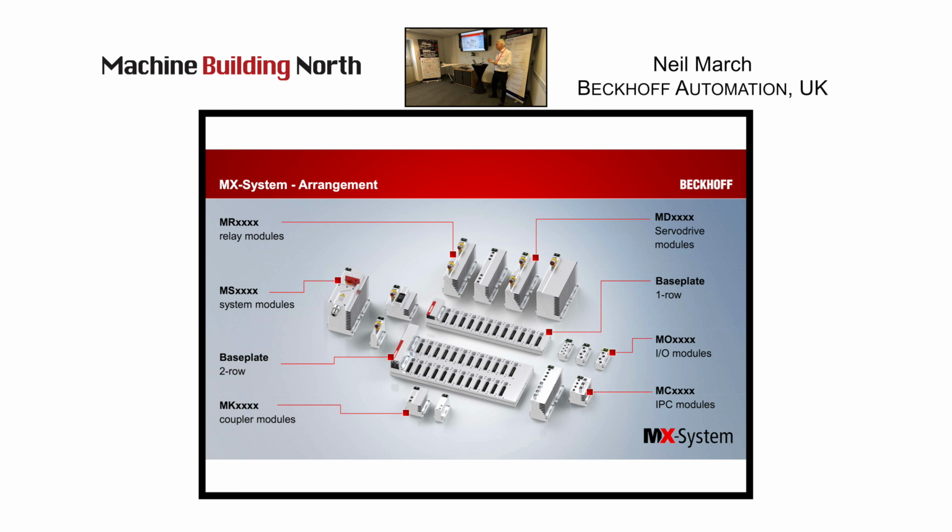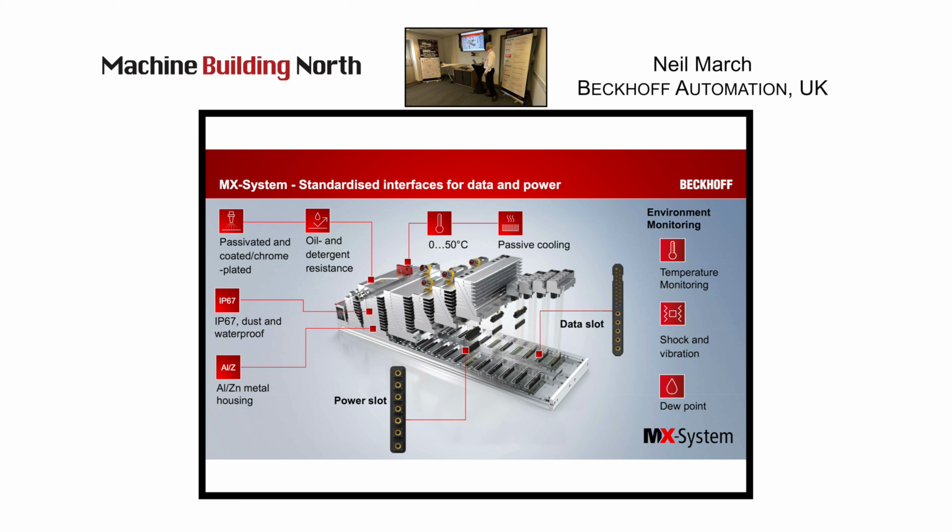But there are different modules of everything from relays, contactors, reversing contactors, AC motors, DC motors, servo motors, and standard relay modules as well. A whole multitude of I/O and couplers, even down to I/O link. Construction itself contains several bus bars, shipping around the EtherCAT communication data, moving the 24, 48 volt data power supplies as well as the AC and high DC voltages. That's all contained within. The modules merely just sit on top.